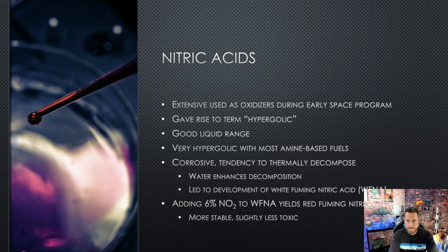One thing that's kind of interesting is that when they were putting the RFNA and the WFNA in the tanks, it was eating away at the tanks, leading to decomposition over time. They had to replace tanks pretty frequently. Just by random chance, they found that if you coat the tanks in hydrofluoric acid, for some reason it inhibited that decomposition process. From there, they started mixing the RFNA with fluorine,